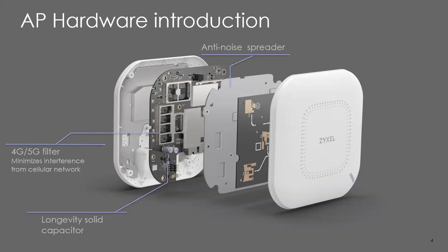The other major cause of failure over time is heat fatigue. As solid state components are exposed to large amounts of heat, it can cause the individual switches inside the chips to start to fail. It could also cause some of the solder joints to crack and create separation, so you don't get as good a connection as you need. To combat that, all of our housings are designed with a lot of vent holes to allow heat to escape from the housing. Some of our competitors have no vent holes at all, so there's no place for that heat to go. On top of that, we have a giant heat distributor, basically a heat sink, that goes behind the PCBA and draws the heat off the board and helps vent it out of the top of the unit. That keeps those solid state components from suffering from heat fatigue over the long term.